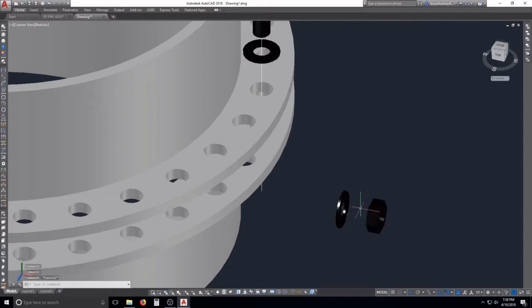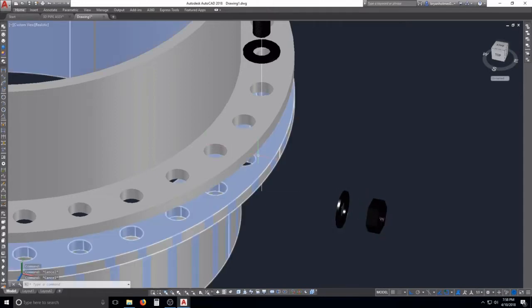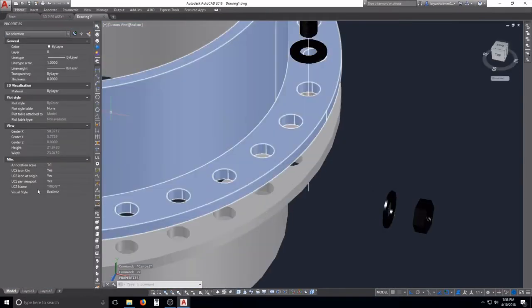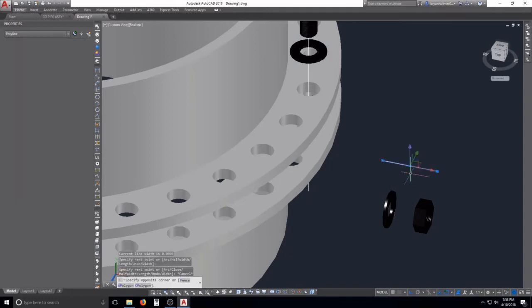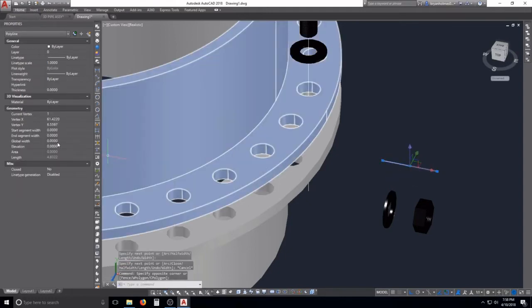You can type in a polyline, and the reason we're going to use a polyline is so that whenever we go into our properties box editor here, so if I just draw a polyline really quick and we'll highlight it, you get a global width on this thing, which thickens it out, creates an easier visual for the person putting this thing together, or reading it, or if it's in a manual or whatever.